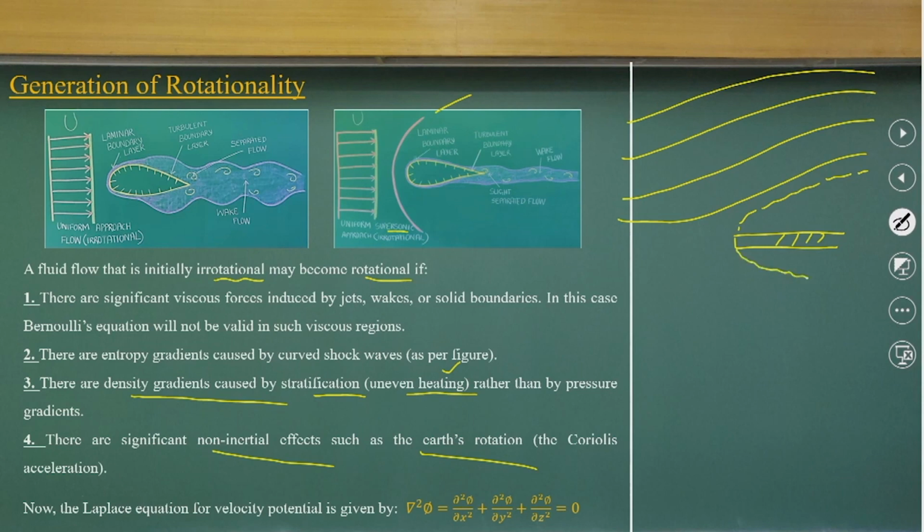we will discuss in the next chapters how the boundary layers are linked with Euler methods to solve these problems, instead of solving the Navier-Stokes equations. The reason is that outside of this part, viscous effects are not dominant. That is why we can use Euler equations to solve these problems. Or if you know the streamlines, you can just apply the Bernoulli equation to solve the problems.